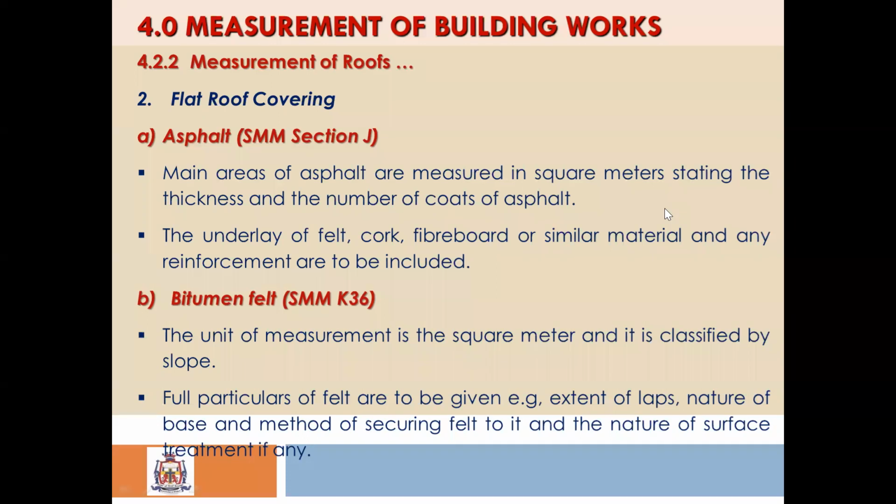Because sometimes you may use asphalt or you may use bitumen and other materials. Now, if we are using asphalt, the SMM section J will cover that. If we are using bitumen, SMM K36 will cover that. And at this point, I think people have made their homework to get the SMM for East Africa.